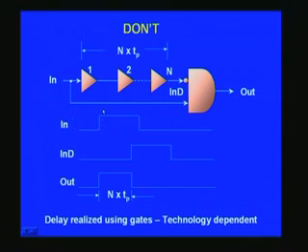Of course, you can't straight away have that. You may have to have proper debouncing, and that is implied here. And this output here is nothing but the same input after a delay. So this is the delay that you have. This delay is governed by the total number of buffers that you have, and that total delay appears at the output also. So if you combine these two in this fashion, with note of the bubble here, then our outcome is a single pulse, the duration of which is governed by this n times TP.